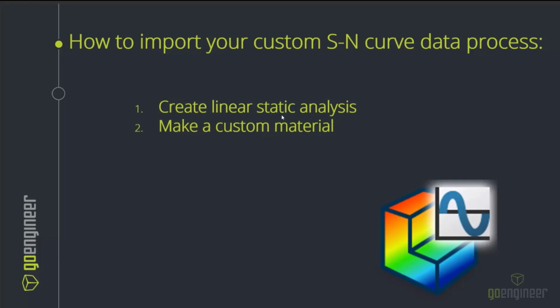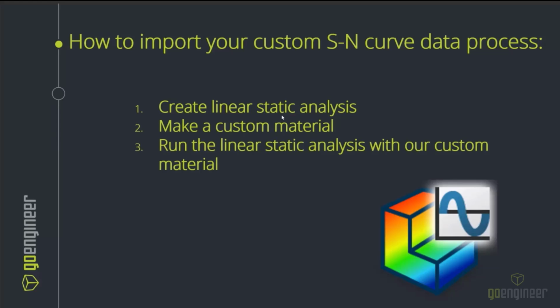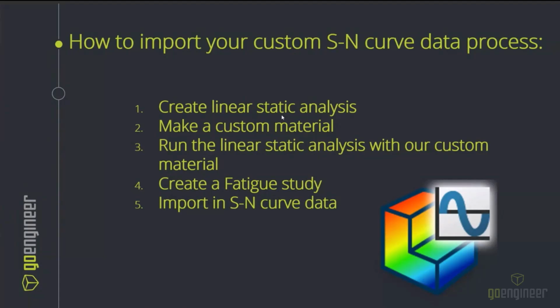That custom material will be used for the fatigue study, because that's where we're going to input our SN curve data. We'll run the linear static analysis with our custom material. We will then create a fatigue study, and then import our SN curve data using that custom material that we created in our linear static study. So that's the recipe of how you go about doing this correctly.